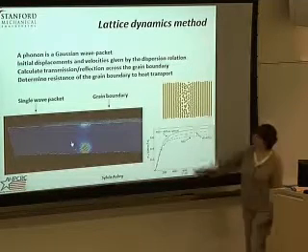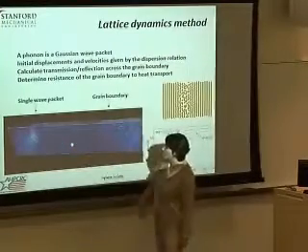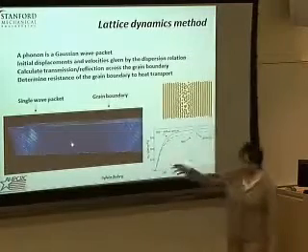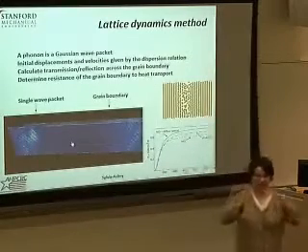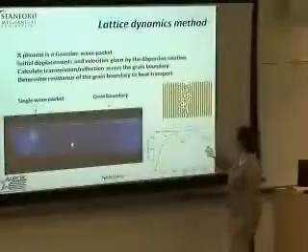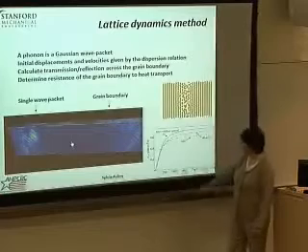Yeah. So you see the phonon starts, and here it hits the grain boundary. Some of it is reflected, some of it is transmitted. And you can do that with different phonons that hit the boundary at different angles. And if you do all these simulations, and that's actually pretty expensive simulation, you can get this kind of curve, which is the Kapitza conductance as a function of temperature.